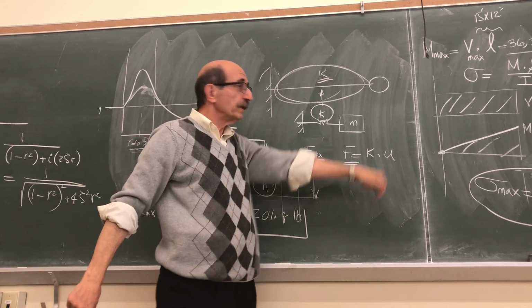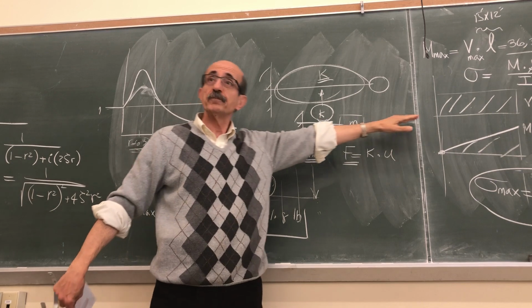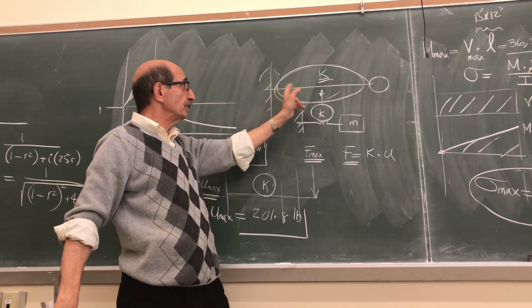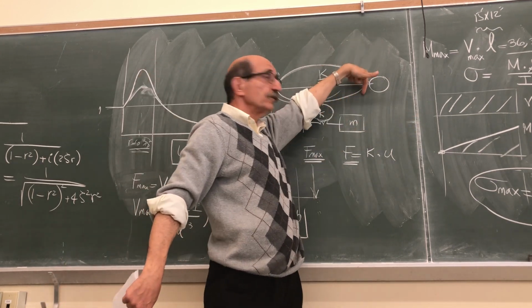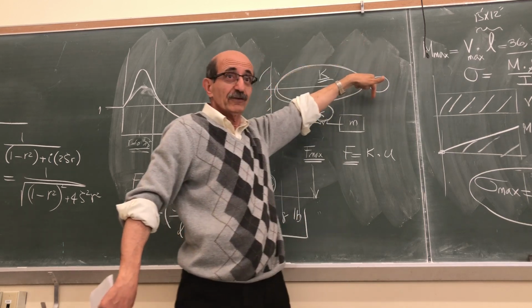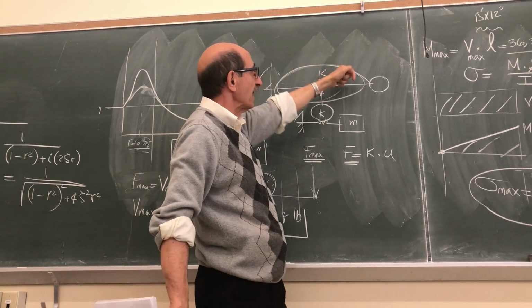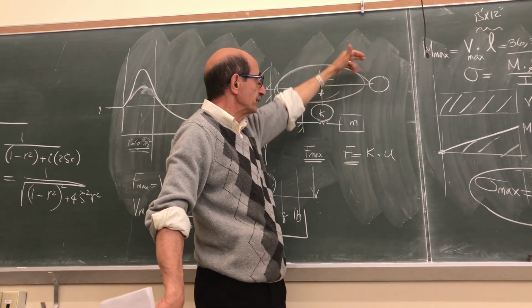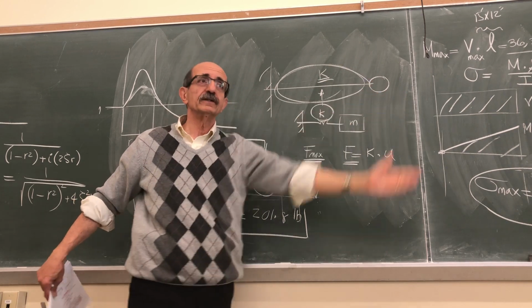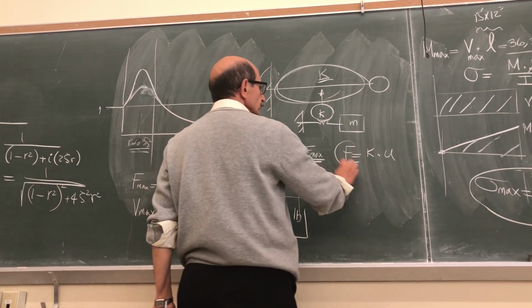is the force that causes deformation in the direction that this spring is resisting. In the case of the beam, this is the force. And although this is perpendicular physically or geometrically, that's actually what is resisting it. So the force represents the shear in the beam. So always remember that this is really the shear force.